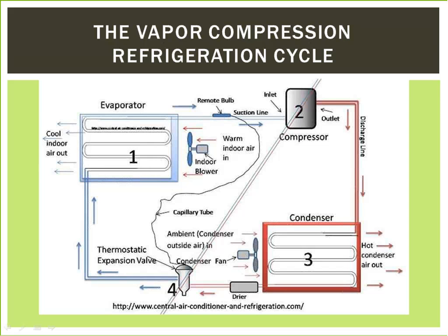With the exception of absorption chillers, most commercial air conditioning systems are based on the vapor compression cycle. The process can be used to collect heat from air, an air conditioner, or from water, a chiller. It can reject the heat into air, being air-cooled, or water, being water-cooled. The process can even be applied as a heater by moving heat from the cold fluid or outdoor air to a warm fluid, which is indoor air. This is referred to as a heat pump.